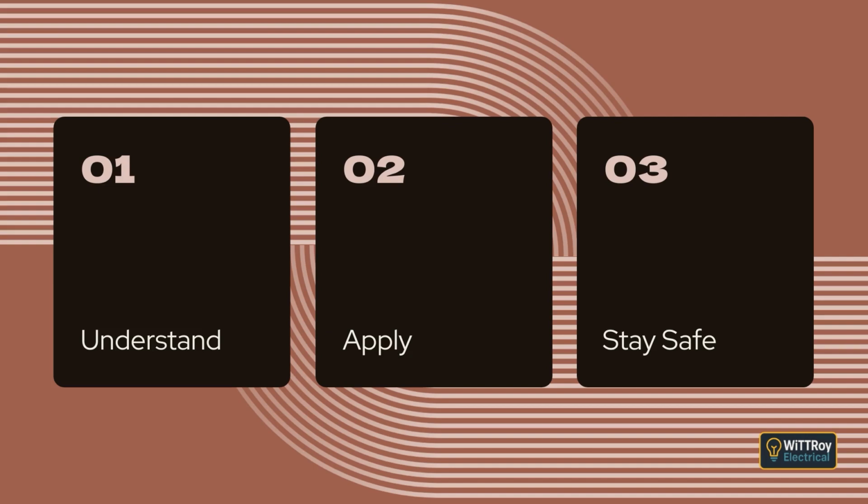When choosing the correct capacity, we must allow for external influences, including thermal insulation around the cable. In New Zealand homes, wiring must be selected with the assumption that thermal insulation in ceilings, walls and sometimes floors may be added in the future, even if it is not installed yet.